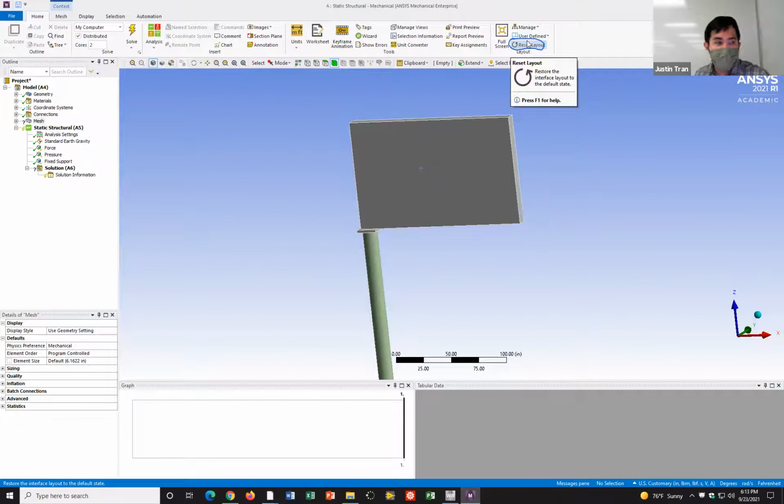Carrie, yes. They don't have to be different, but I want you to apply settings for both the sign and the post. Yeah, but if you think it's appropriate to use the same settings for both, then you can do that. But remember, you want to concentrate the mesh density and have your small elements where you think the maximum stresses are going to be.